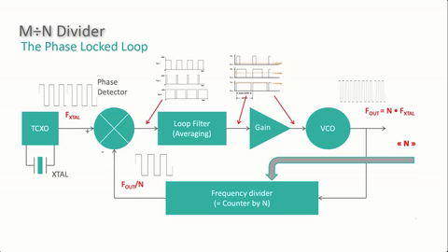Now, for a lot of PLL designs, this makes a lot more sense than a true bipolar design with 0 phase shift. The loop filter and the gain block smooth the pulse train to create an average DC level. At a 50% duty cycle, the average DC level should be exactly 1/2 the full range voltage, and a smaller or larger duty cycle causes the DC level presented to the VCO to rise and fall as well. Now, assuming the VCO has a wide enough range, increasing the frequency divider's divide ratio will make the VCO output frequency increase. Put in a 1 MHz crystal, set the divide ratio to 10, and you'll get a 10 MHz output.